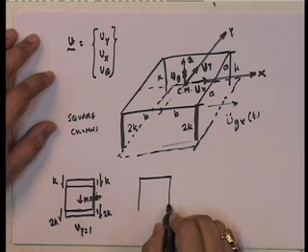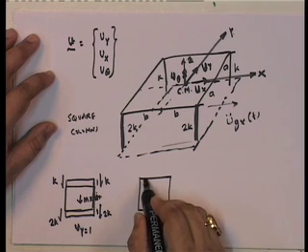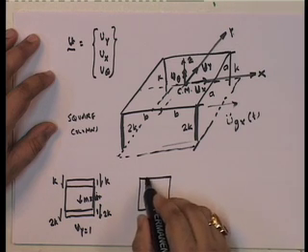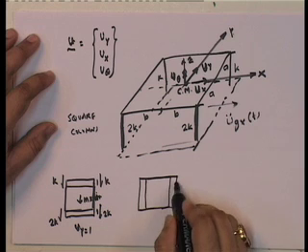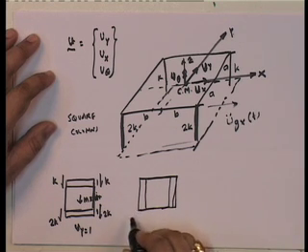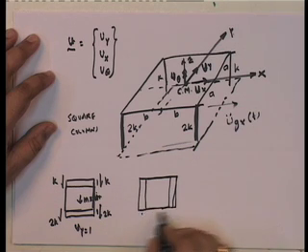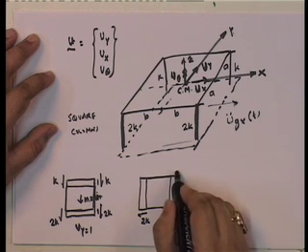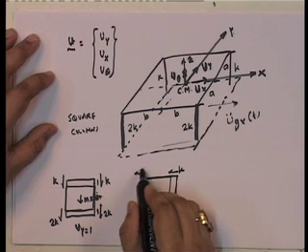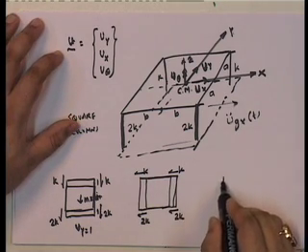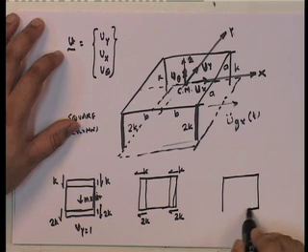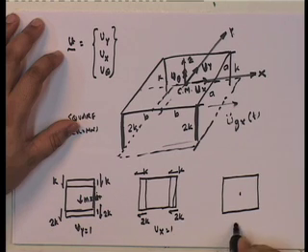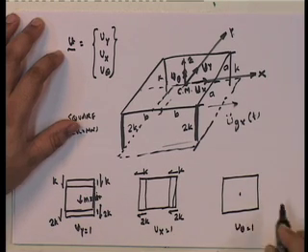Okay. So, what we have now is, having put it this way, let us put x direction. So, if I have x direction displacement, I have this way. Okay. So, again, since it is gone in this direction, I will get 2k here, I will get 2k here, I will get k here, and I will get k here. Okay. And finally, what we need to do is look at, this is V x equal to 1, and the final thing is V theta equal to 1.